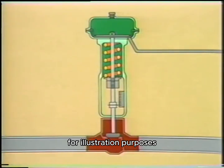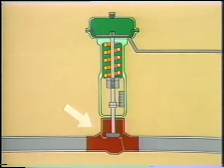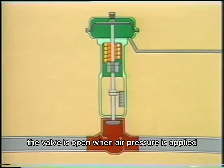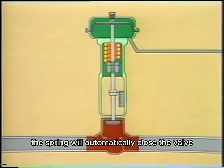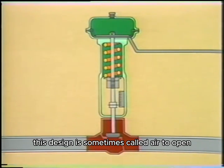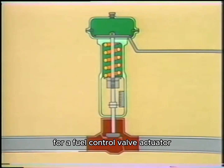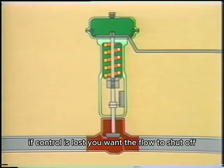For illustration purposes, let's attach a valve to this actuator. In this case, the valve is open when air pressure is applied and the stem is up. If control air is lost, the spring will automatically close the valve. This design is sometimes called air to open, spring to close. This would be the preferred design for a fuel control valve actuator. If control is lost, you want the flow to shut off.